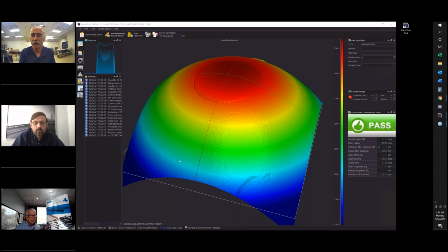But I pushed this particular one for the ability to reach down inside. And they've got innies and outies. In other words, besides being inside of a cleaner, it's embedded in plastic. It's external to the plastic. It's available to actually go through the alignment sleeve. I'm not a big fan of going through alignment sleeves unless that's the only way you can get to the surface of the zirconium. Why? Because you're always putting that C-shaped piece of zirconium at risk. And like I said, when it breaks, it's good for 10 to 20 dB of attenuation. The glass no longer aligns. Okay. I wasn't exaggerating when I said that little $10 part is going to look like a broken connector.